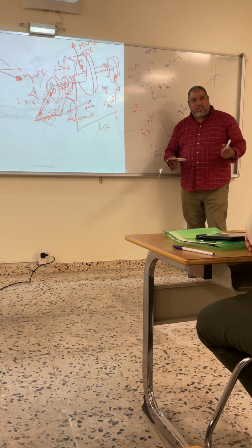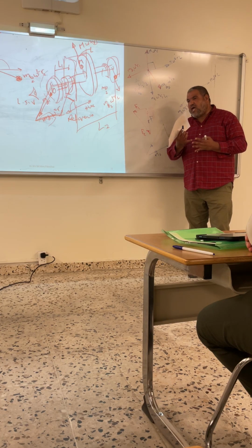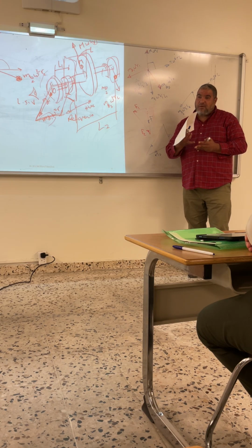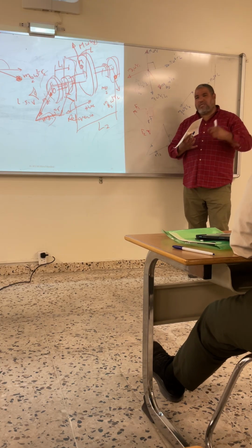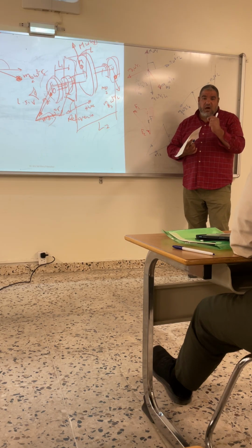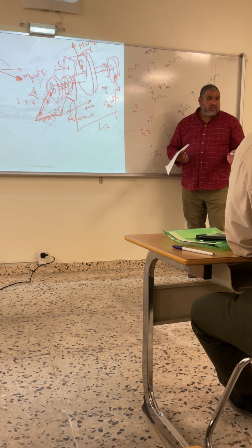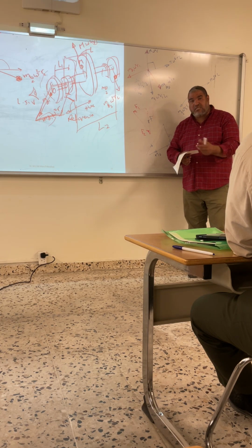Why am I not able to get M separately and R separately? Because actually you will end up having three unknowns, M and R and theta, right? So usually we are looking for the MR product. Is it good or bad for our case? It's good because it gives us flexibility. You can locate your balancing masses at any R you like, and then choose the mass. But if I fix the R, then you have to fix the M. Having the MR product is good. Although from a mathematical point of view you end up having three unknowns, you decide to make it two unknowns by coming up with the product. This is mathematically, but practically speaking, this is very good.